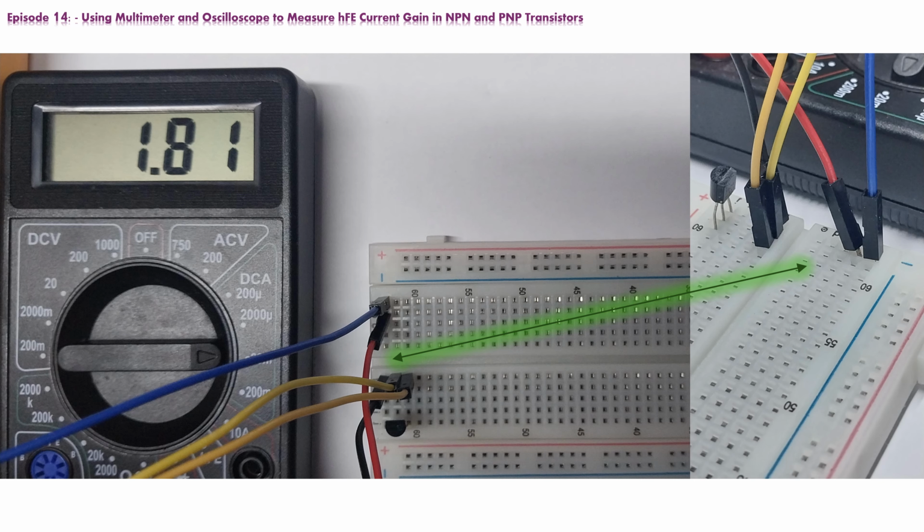Now, there is no more mystery. To measure the hFE parameter for NPN transistor 2N3904, our multimeter uses VCE voltage of 2.94 volts, base current of 10.1 microamperes, and there is no small signal present at the base terminal. Now, to verify measurements, we should measure collector current, and calculate the value of hFE for ourselves.